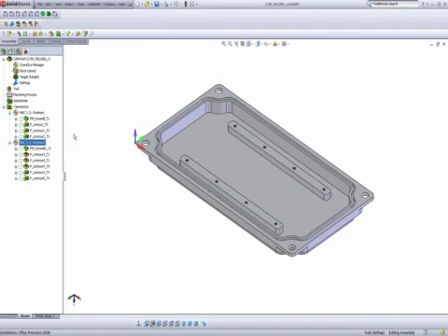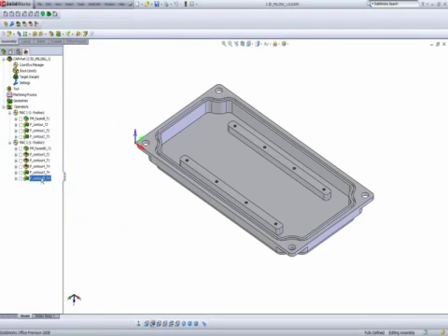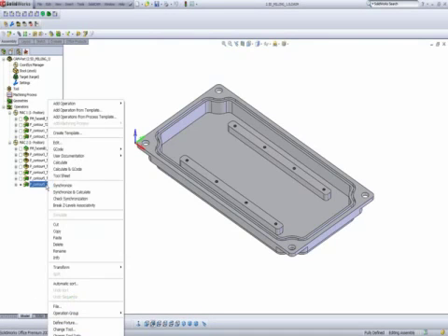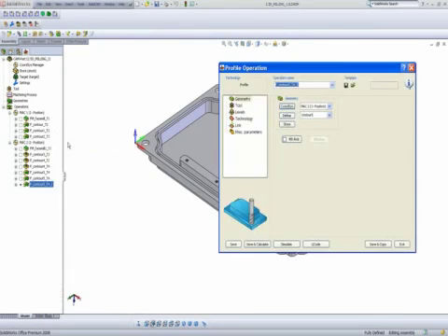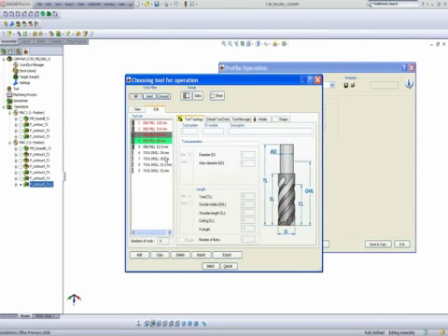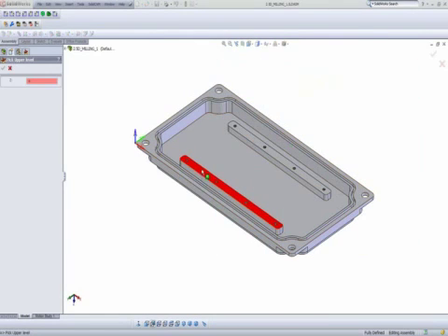If I were to start a new operation, in fact, I'll take this particular operation that I've done before and simply do copy and paste. And again, I'll go in here and make some changes, such as the tool. This time I'll use tool number 3, which is an 8mm in diameter tool. My levels. My upper level will be here.